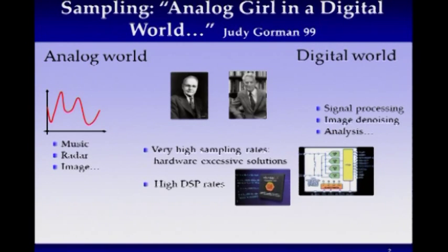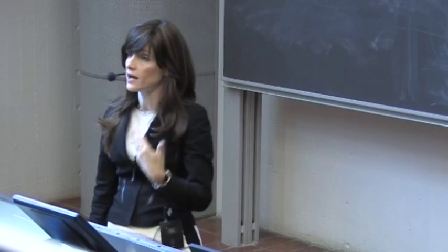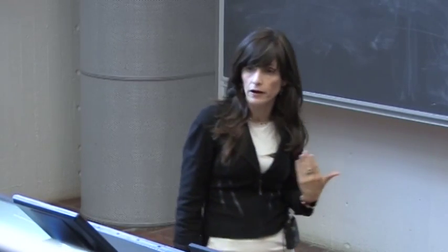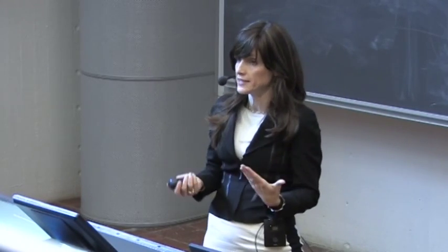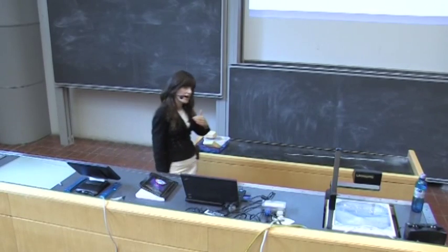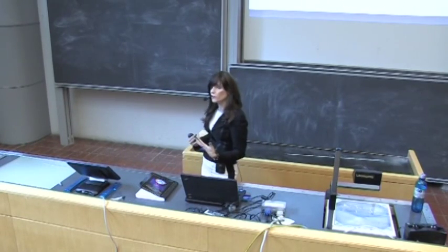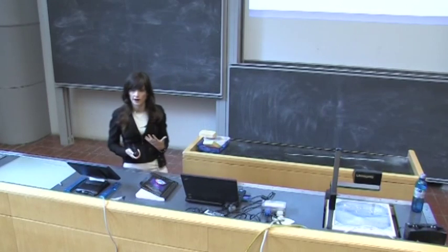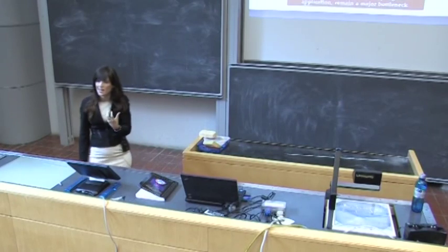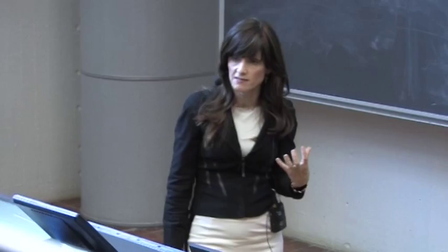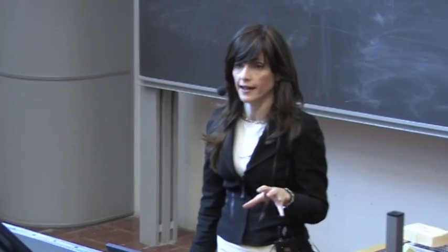It used to be that we would think of analog as being hard and DSP as being essentially free. But today, that's no longer true. In many applications today, what we find is that the DSP rates become so high because of the high sampling rates that we can't keep up with them anymore. Or in other words, trying to keep up with them requires a lot of power and consumes a lot of heat. So we have both the analog problem of actually just sampling at the rates and the DSP problem of processing the data that's coming to us at these rates. So essentially, this basic block of the ADC, which we essentially take for granted, is actually the bottleneck in many DSP applications today. And that's what we want to target in our talk today.